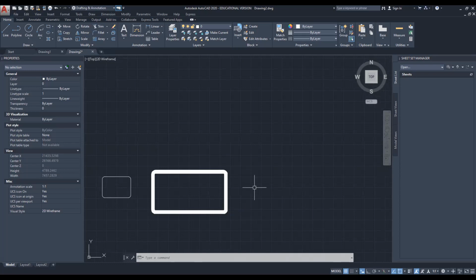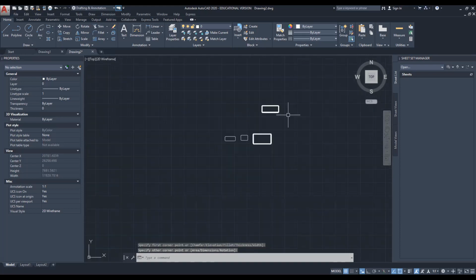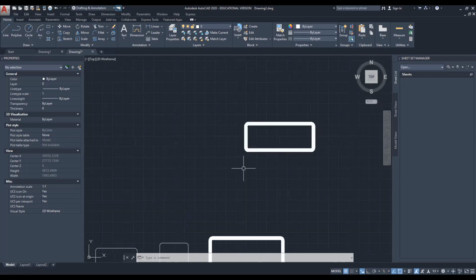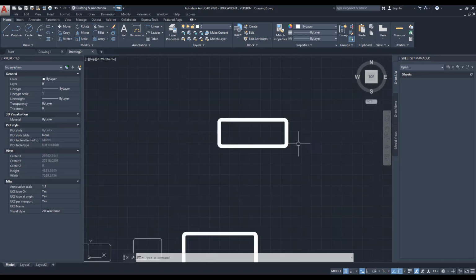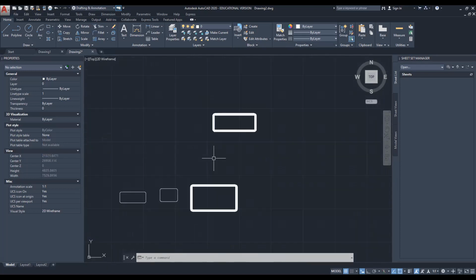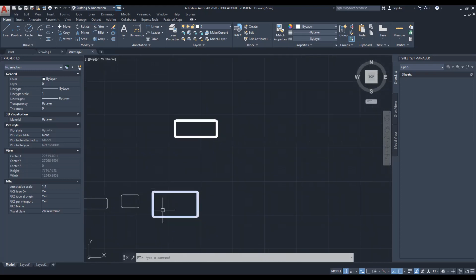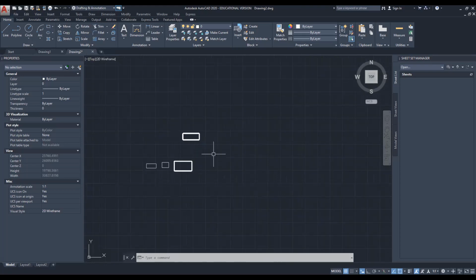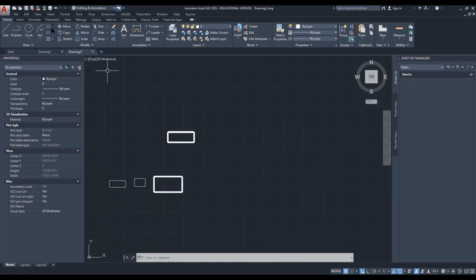After making these changes to the rectangle settings, whenever we try to create another rectangle, we will only get a rectangle having the same line width as before, and also a fillet type of rectangle, because we have already set the rectangle settings to fillet. We have already set some fillet value, chamfer size and line width. For removing those and getting the normal rectangle again, we have to go to the same options again.